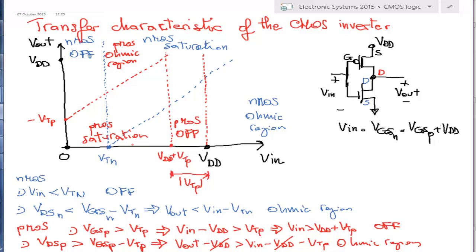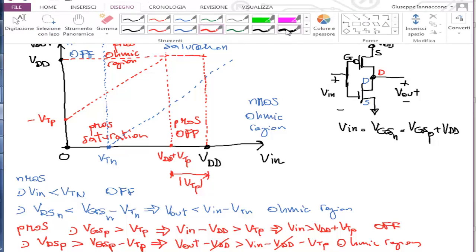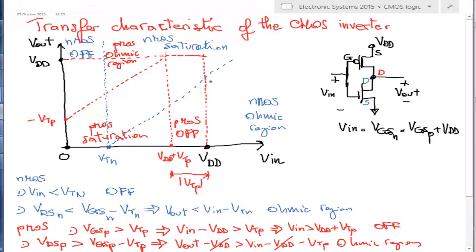so again we have a division. Of course, V out cannot be larger than VDD, so we have a quadrant that is not a complete quadrant, it's a square of side VDD in both directions, but we have partitioned the whole space. Now we are ready to draw the IV characteristics, which is something that is already known to you, but let us do it again.